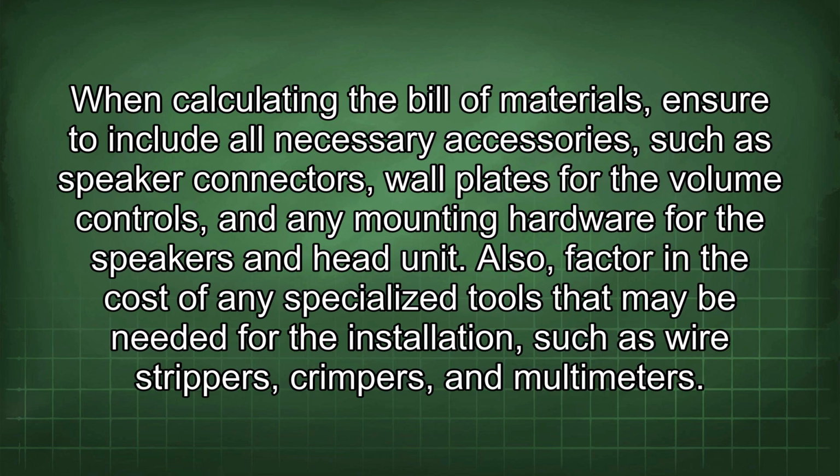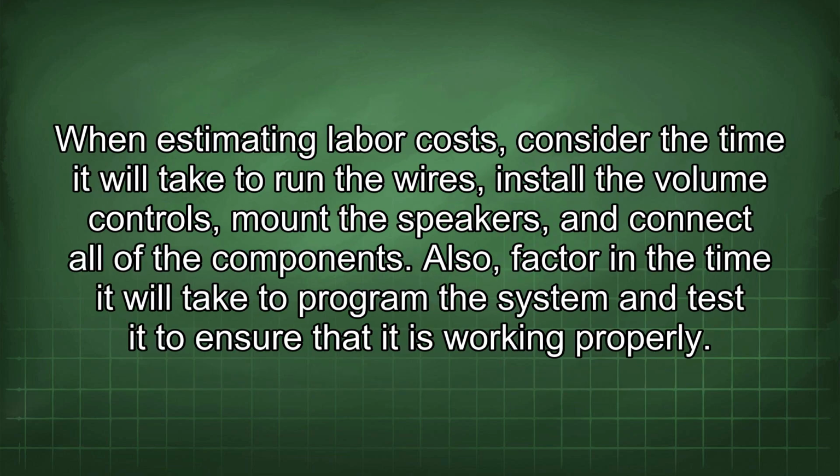When calculating the bill of materials, ensure you include all necessary accessories such as speaker connectors, wall plates for the volume controls, and any mounting hardware for the speakers and head unit. Also, factor in the cost of any specialized tools that may be needed for the installation, such as wire strippers, crimpers, and multimeters.